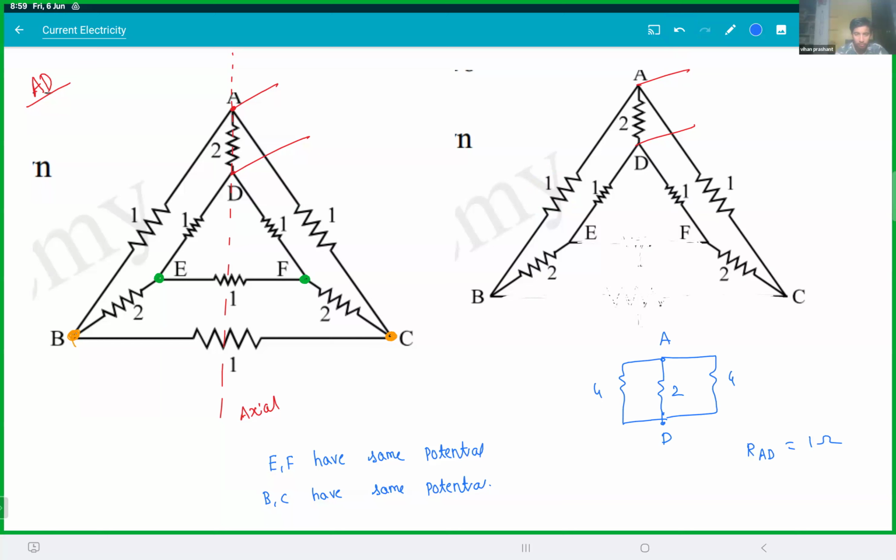Sir, if we fold it, for example, the resistance between D and F would become 2 ohms and AC would become D and F, 4 ohms. Arre God, they're in parallel. Resistors in parallel will become what? Half. They won't double. Capacitors in parallel will add up. Resistors in parallel will become half. When you fold them, what will happen? They'll all become half. Okay, got it, sir. Don't remember like that. When you fold them, they're in parallel. If it is capacitors, it will be C1 plus C2. If it is resistors, it is R1 R2 by R1 plus R2. You double them. Got it, sir.